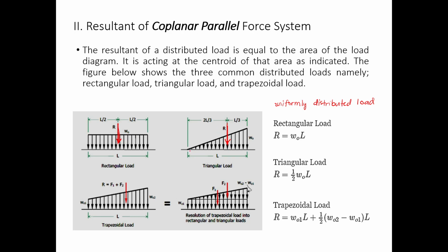If you have a mixed load, instead of determining it directly, I think this one is just approximated, because in a trapezoidal load it will depend on the degree of the load being presented. So you may break it down into two different components, one rectangular and another triangular.